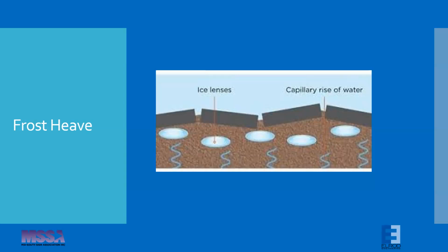If you've got a monument sign, a great example is a monument sign, and the foundation is shallow, just because from an engineering point of view, it didn't need to be too deep. So say it's 2 feet deep, and you're up in mid to northern Kentucky, and you've got a 36-inch frost line. So the soil can freeze to a depth of 3 feet. If you have one of those really cold winters, if it freezes, you can have the differential expansion of the soil such that the monument sign tilts, the foundation actually tilts, and that can create instability for your sign.